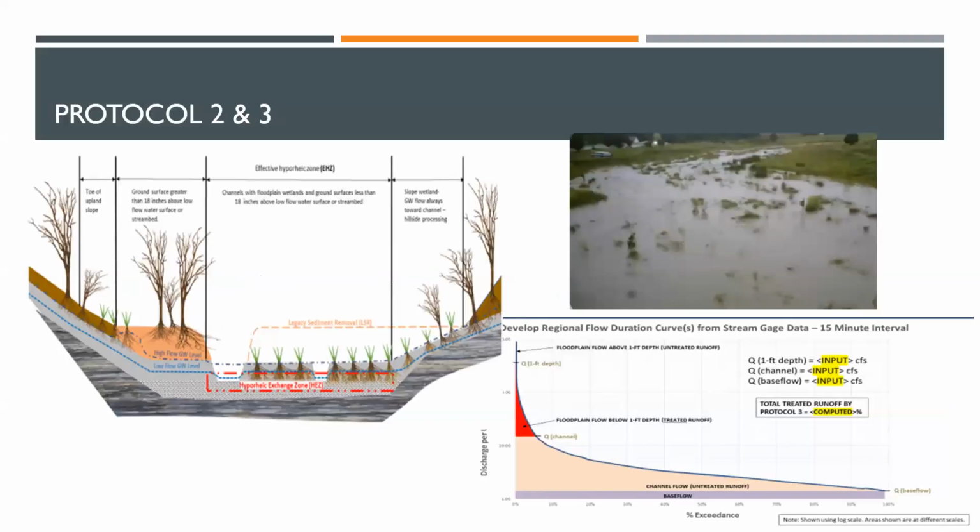But the basic approach here is they're looking at some tweaks to the definition of that hyporheic box. I think it's looking like they're moving towards an areal hyporheic exchange zone. So as opposed to calculating that volume beneath your stream channel, you're going to be able to expand that zone further laterally into the floodplain, but it's not going to be as deep of an area.